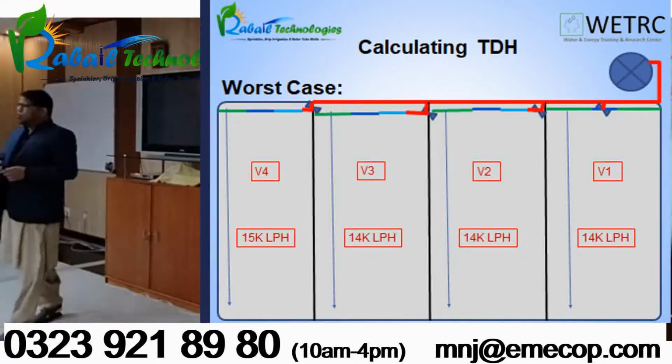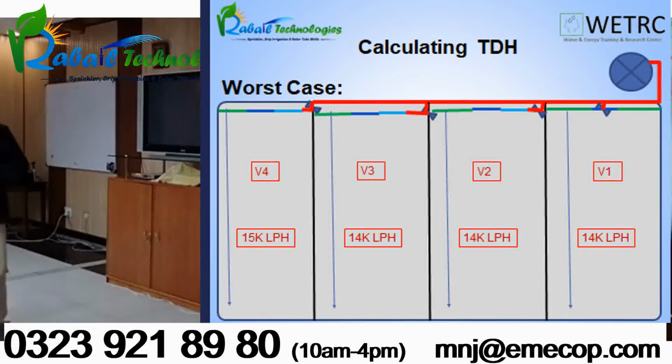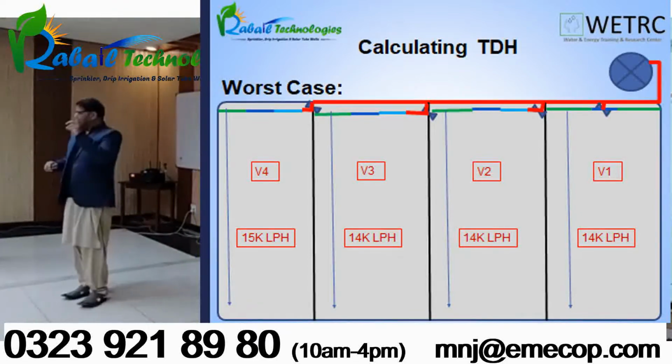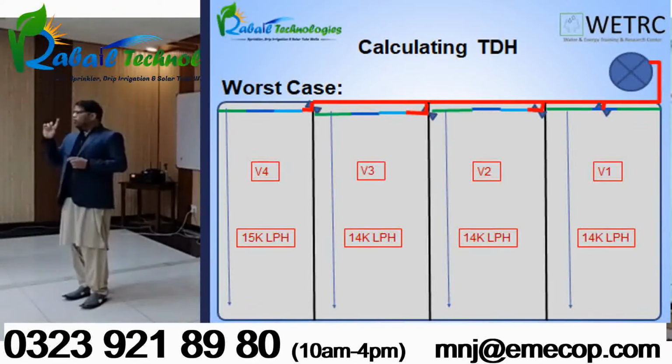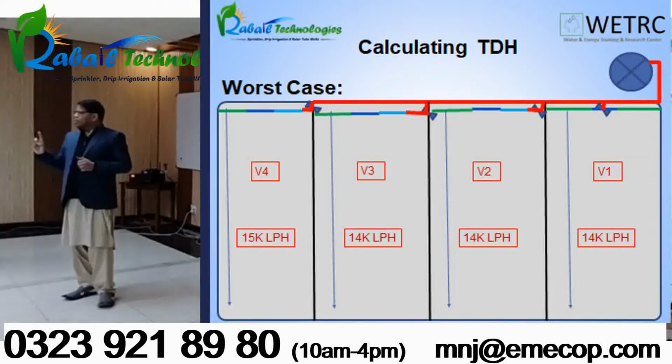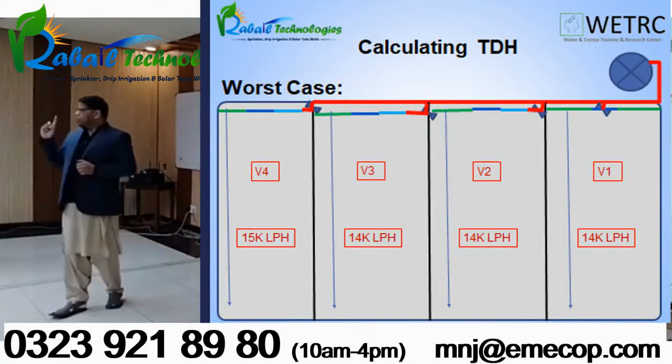So these are the two, and for example, that red pipe indicates 3 inch piping. So we have diameter, we have length, we have flow rate. We can easily calculate the friction losses. But remember the F factor. The F factor is valid only for the sub-main and for the laterals. For the main line, the F factor will always be 1.